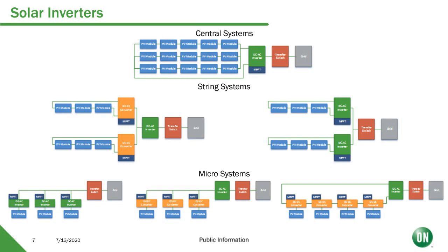you have different types of systems. You have a central system that normally combines all the different solar modules and then does the power conversion from that. This has typically been how solar utility scale implementations have been done in the past decade or so. One of the concerns here is if one of the solar modules fails, that causes a whole system failure. So downtime is never good and causes issues with reliability in the grid.